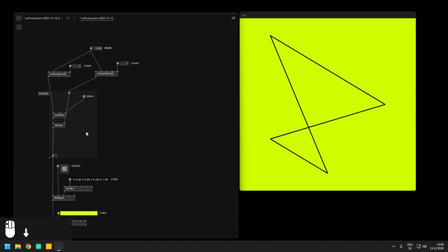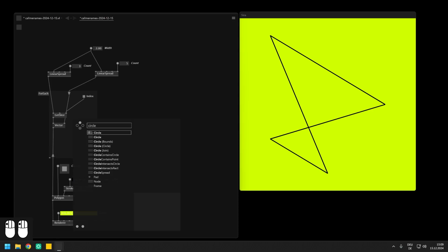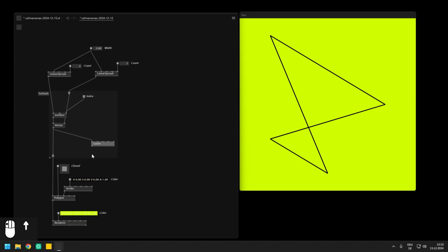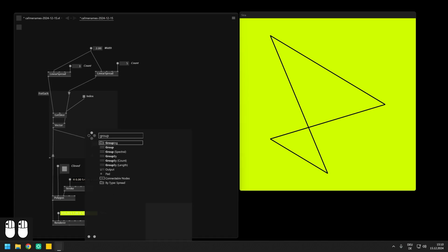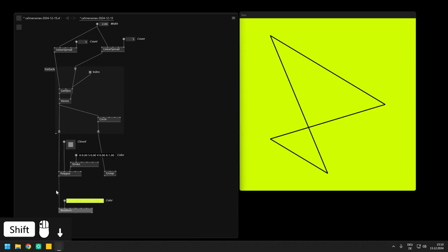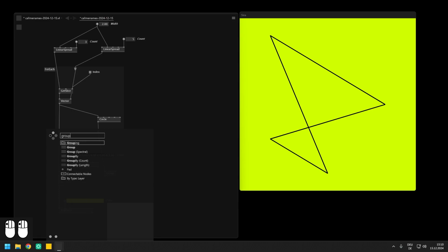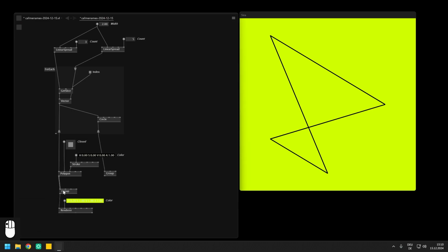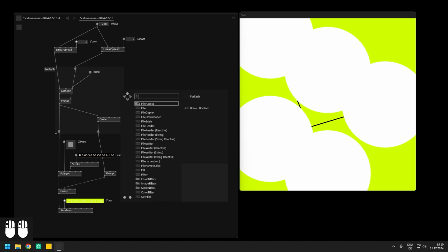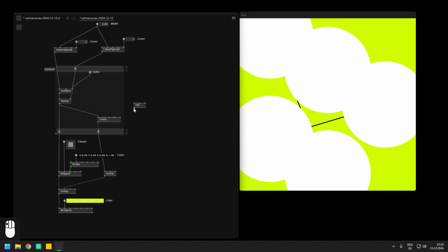We can visualize this even clearer when also drawing a circle on the positions inside of the loop, so collect them with the group node, and combine its output with the layer from the polygon. Let's also send in a fill node for which we use the same color as for the stroke, and also decrease the radius of the circles to a smaller value.